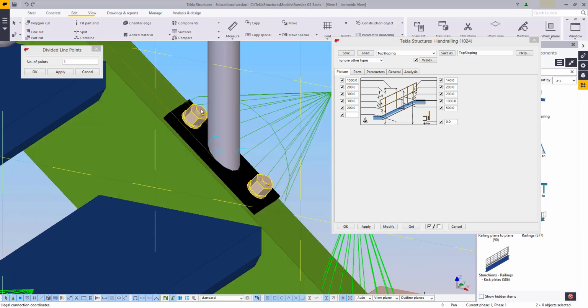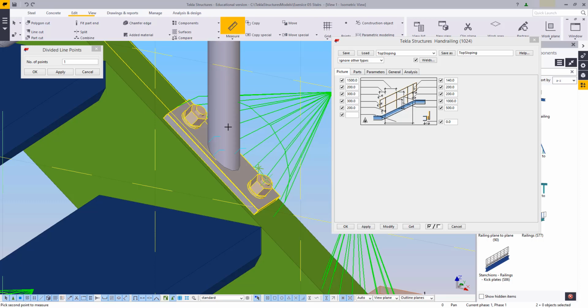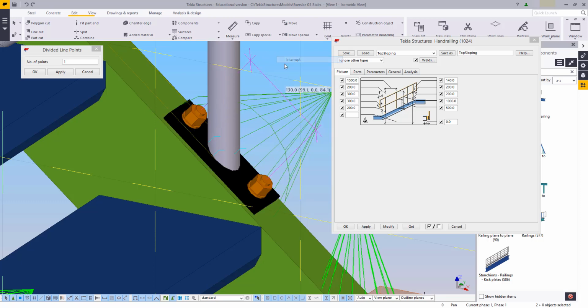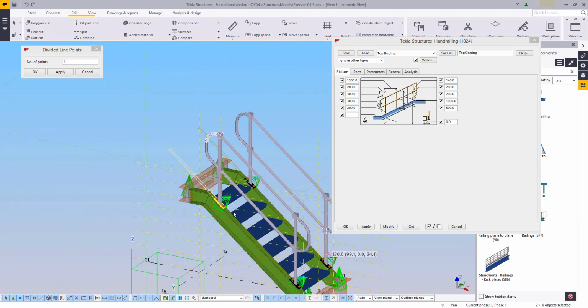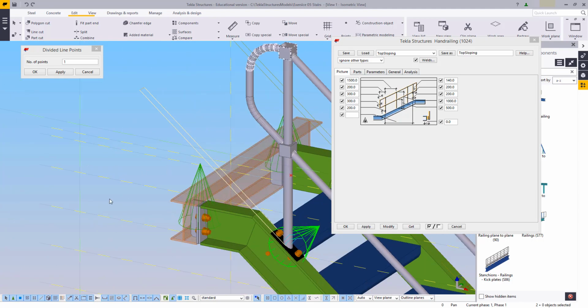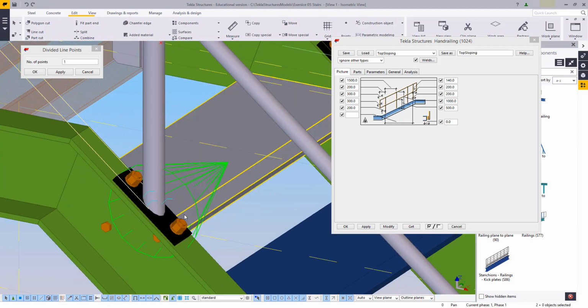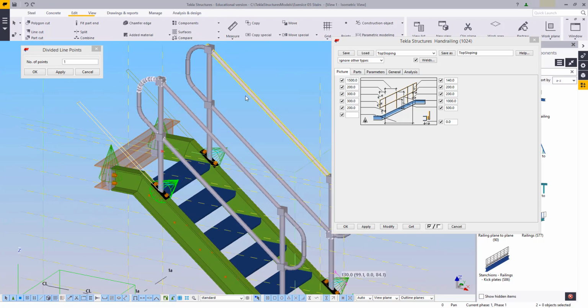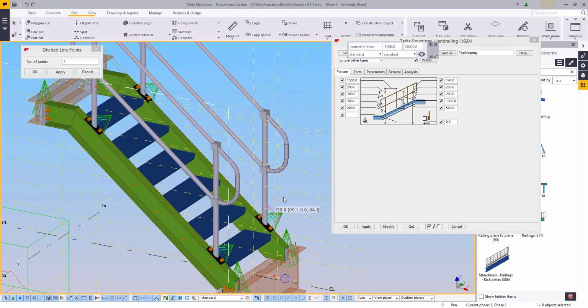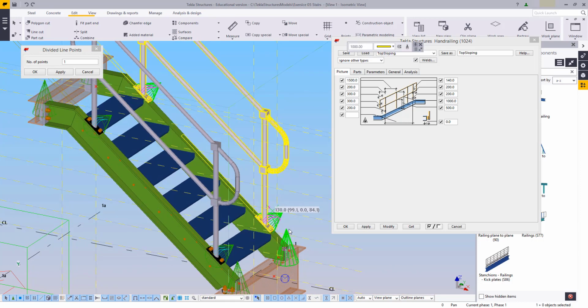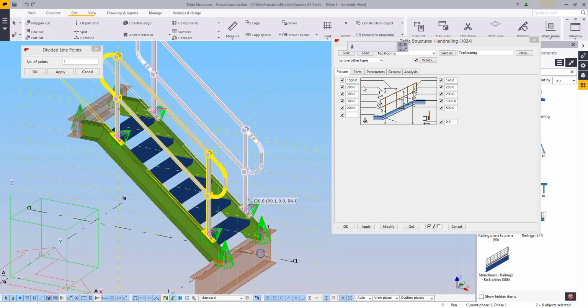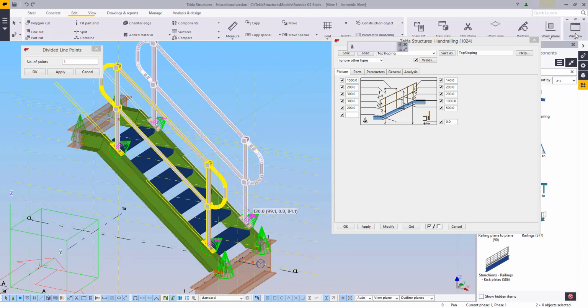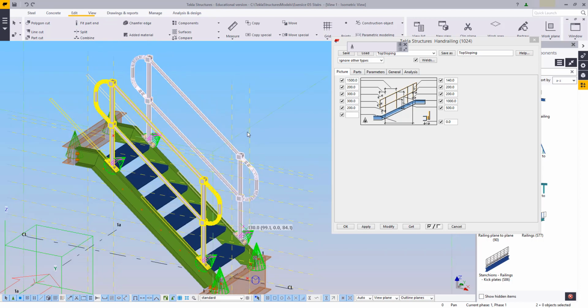So the distance between these two holes on sloping is 130, whereas if you're doing it on the top of a floor, it's only 100. Do note that this is specific to the port-out hand railing that we primarily use in South Africa. Yours might be different, or your company might have a custom set of hand railing, as most of the mines do.